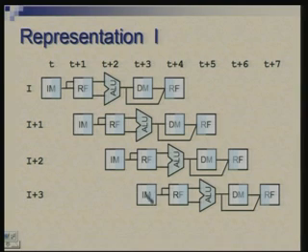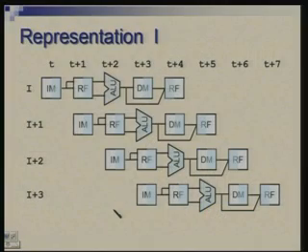If you do want to share, you can put a multi-port memory here, this could work, but practically these memories are not multi-port, and therefore it makes sense to keep this structural hazard away by having two separate memories. Okay.